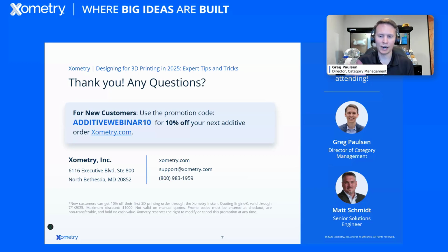Yeah, absolutely. All right, I got one. So you offer stereolithography. Do you also produce ceramic parts? If so, what resin slurry manufacturer, and is it manufactured in-house or by external suppliers? So true ceramic printing, we have some discovery on that, but it is very touchy because ceramic parts often will shrink about 25% or more from their net. And what I'm talking about is true ceramics, going to be in very, very high heat conditions.